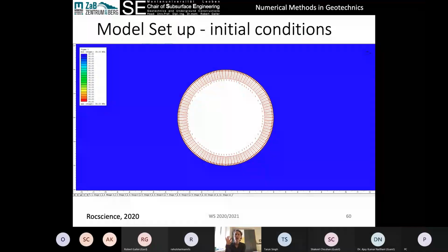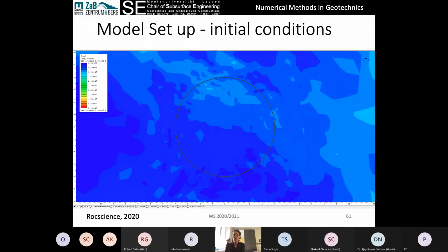We have to put in the most appropriate stresses, and then we have to run the model. The model must be initialized to allow all of the minute deformations to occur, especially if we're using gravity, to allow the model to compute what the gravitational stresses are and allow any sort of movement. We visualize it as movement.